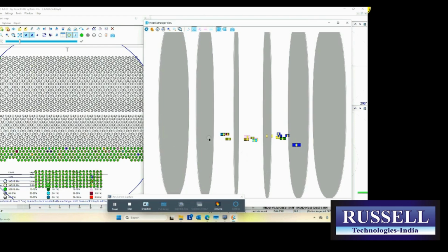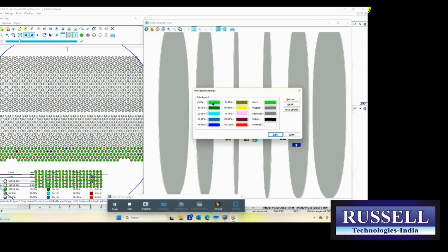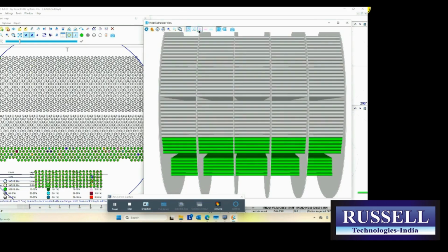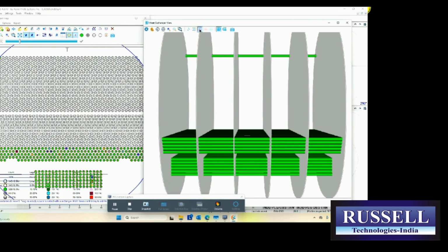And now you can put that in your report and say, okay, here's the front tube sheet where we did our inspection from, here's the back tube sheet, and the defects are grouped between tube sheet number 1 and tube sheet number 4. If you want to change the color palette, you can use these colors here, or you can match the colors that are in the legend for the end view, which is what we would recommend. So once you're happy with all the colors, you can just apply that. You can then go back to the full tube view or just the inspected tube view.